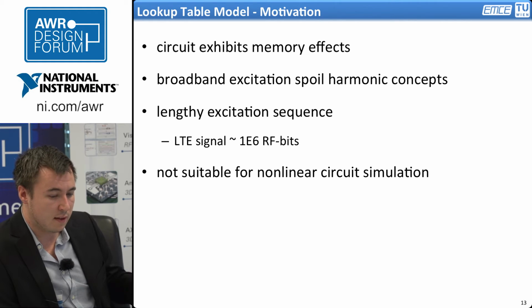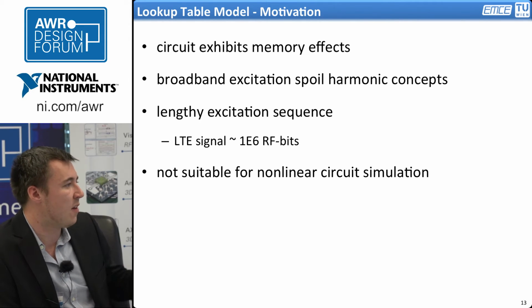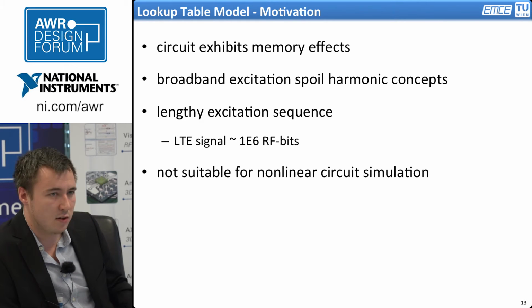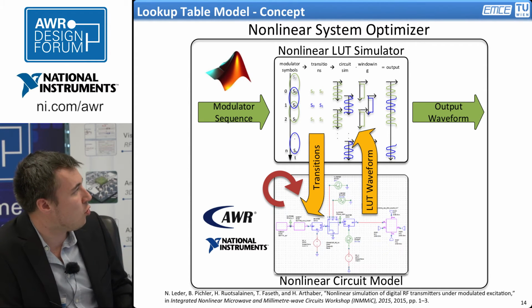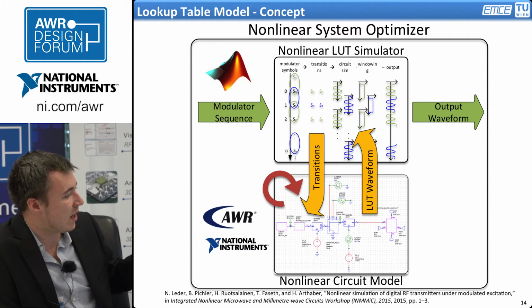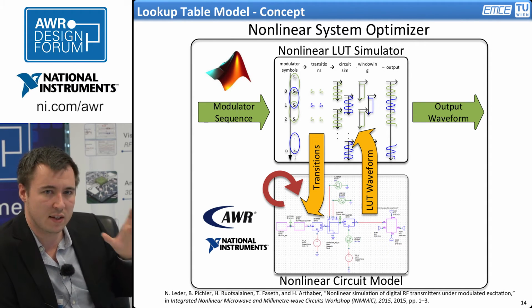The broadband excitation that has this very lengthy excitation sequence spoils classical harmonic concepts, since we would nearly have an infinite number of components to consider, and therefore it's not directly suitable for nonlinear circuit simulation. On the other hand, an interesting aspect is that we can group this excitation sequence into subsequences that are just long enough to capture the typical memory effects present in the circuit.